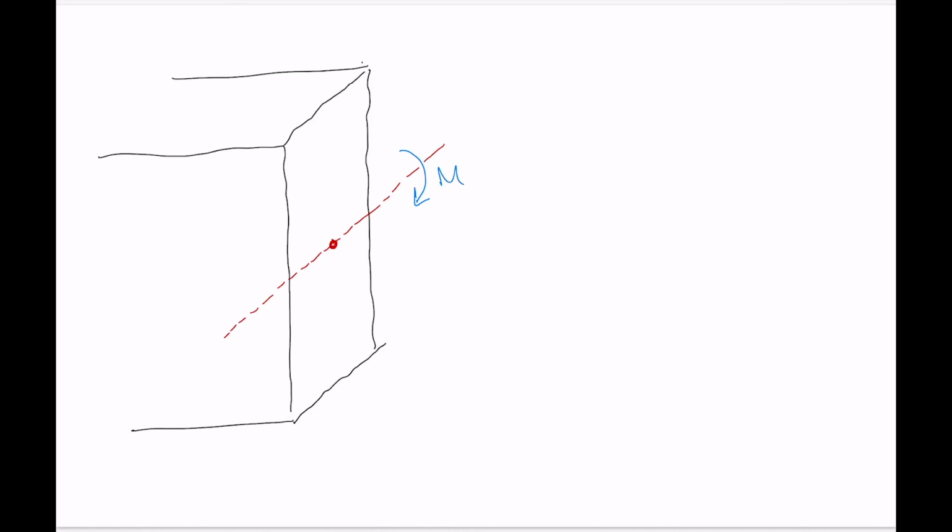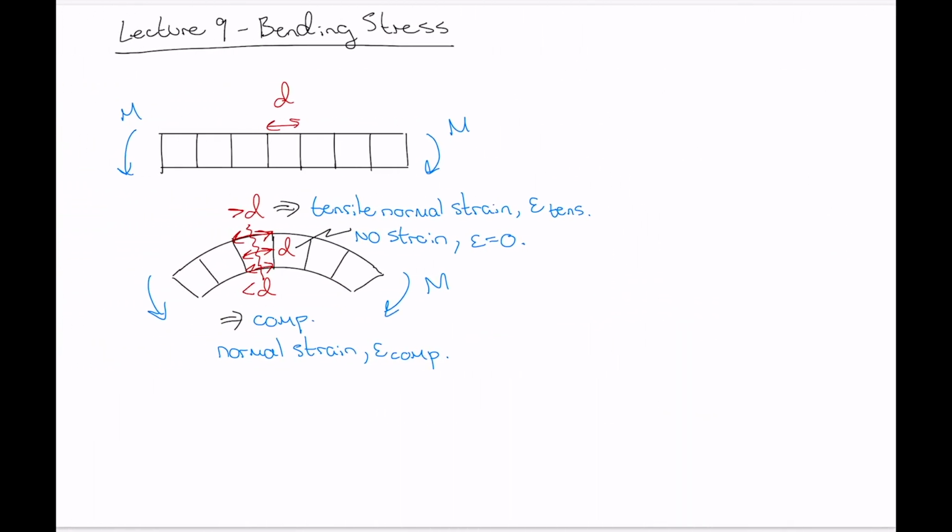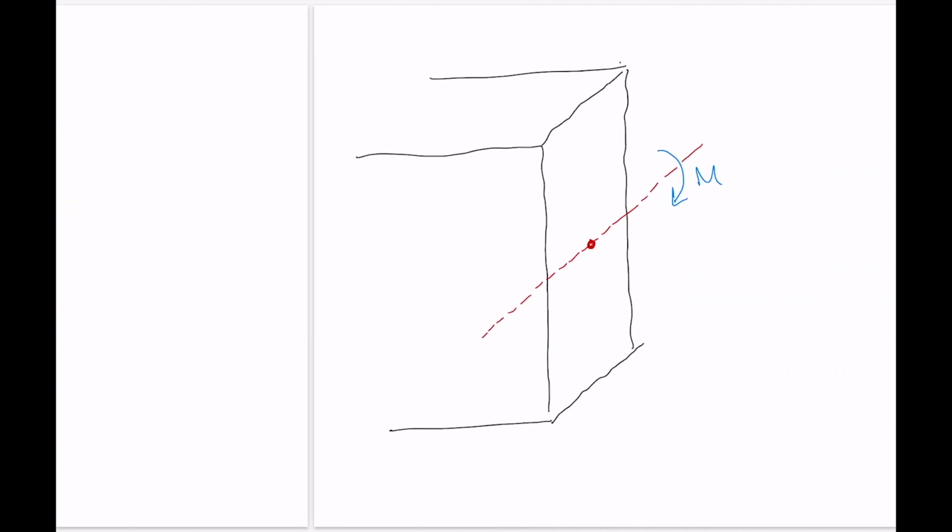So if I flip back to the other page here, we're drawing this section cut. If I was to do the quick doodle on this page like we usually do, just to show you what we're doing, we'd have this moment here, and then our internal moment would be acting in that direction. So it's this portion of the object that I'm drawing on the next page, but in 3 dimensions. So our section cut, the internal moment, and the remainder of the beam going out to the left. So here it is there.